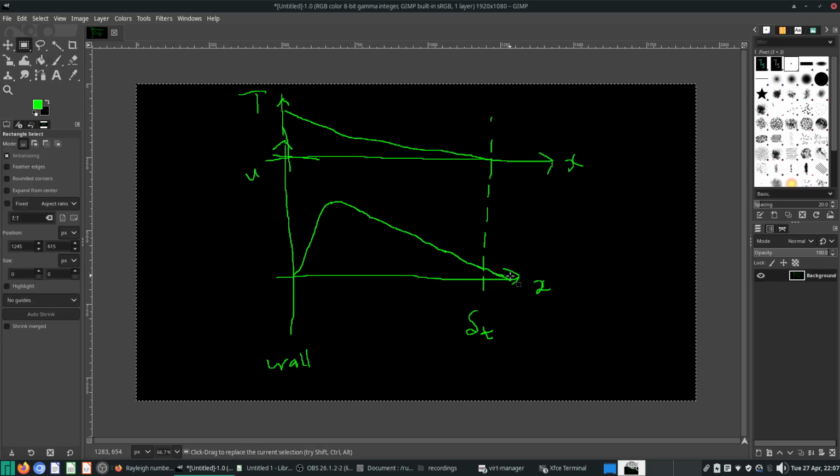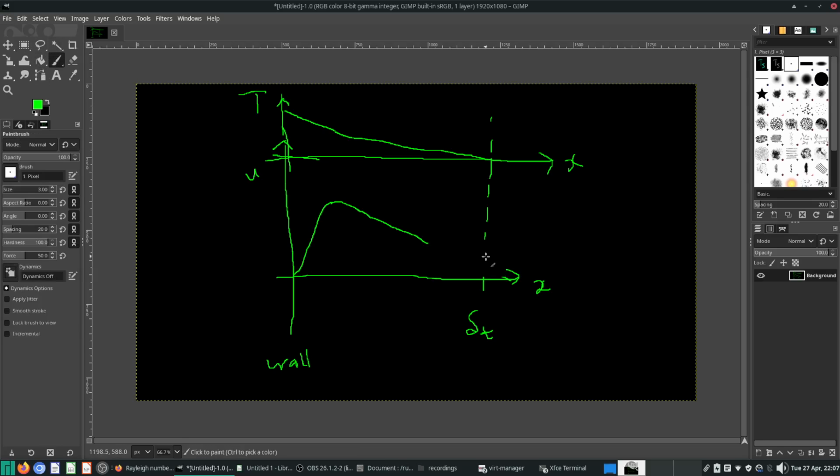Okay, so in general, if you look at Bejan's textbook, Adrian Bejan's textbook on convection, you'll notice that in his diagrams, the momentum boundary layer thickness will be thinner. Okay, the momentum boundary layer thickness will be thinner than the thermal boundary layer thickness for Prandtl number much lower than 1. Okay, so this is the liquid metal case.